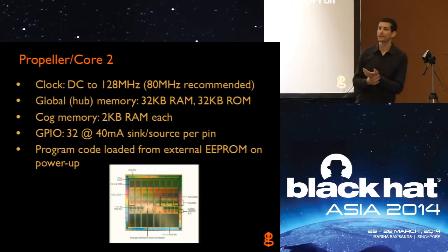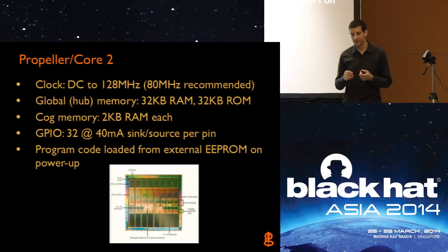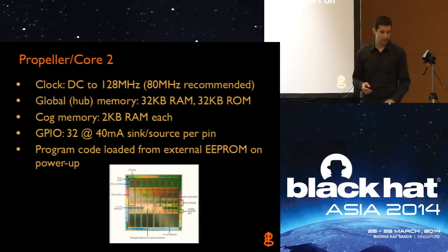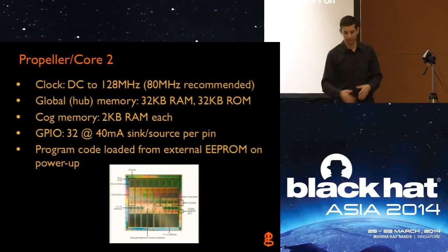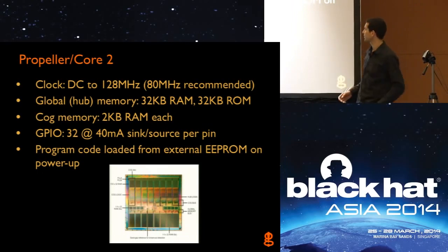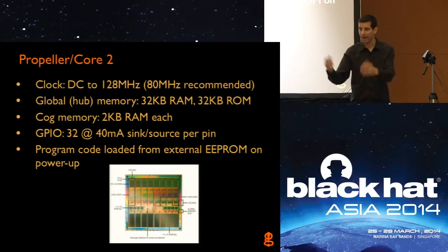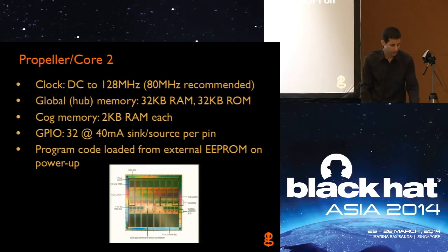And one of the things I wanted to do when I was designing this tool is find a processor that had lots of pins, but also had an easy way to program it and didn't need a weird, large development environment and all of this stuff. So trying to find that balance. But 32 pins, we're using 24 of those pins for I/O, and the other stuff we're using for the analog to digital or digital to analog converter and stuff. So it's a pretty good number. You could always design a similar JTAGulator with an FPGA with 128 pins or something. So you could potentially get larger I/O, but I think 24 is sort of a good number for now anyway.